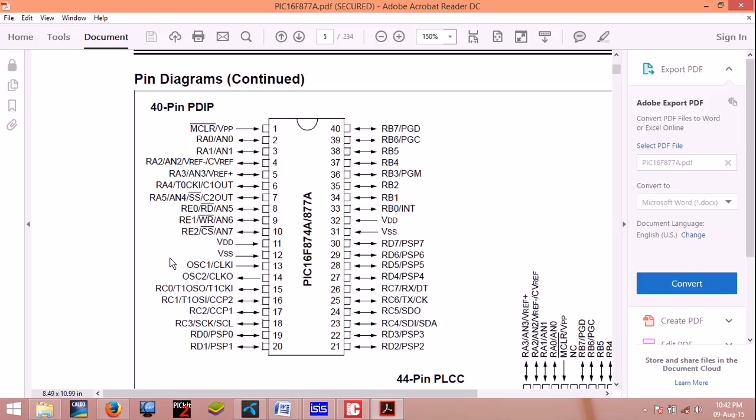A microcontroller has an internal 4 megahertz frequency, but for the betterment of the microcontroller, so that commands can be carried out carefully and fast, we have to use an external crystal. So we will be using the 20 megahertz. Here you may get confused seeing VDD and VSS on both sides. You don't need to be frustrated about that. You can use either side, it doesn't matter.